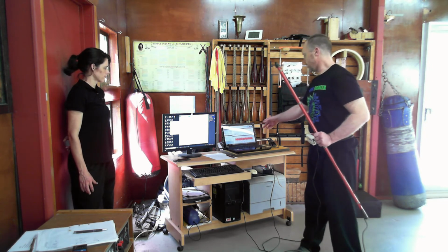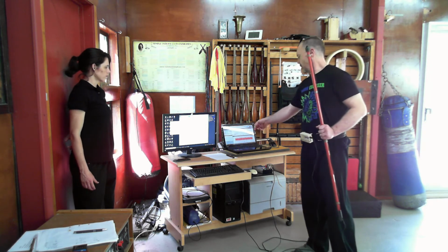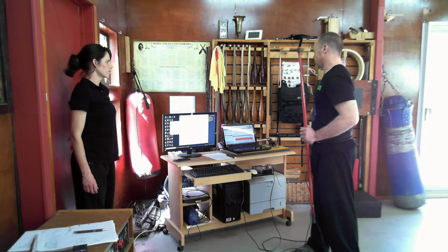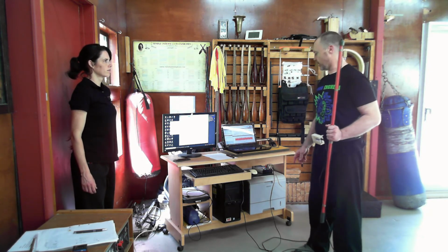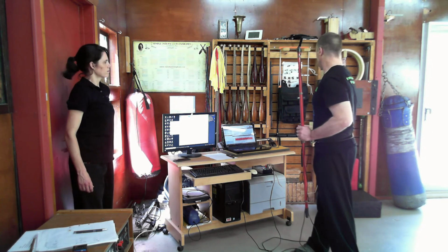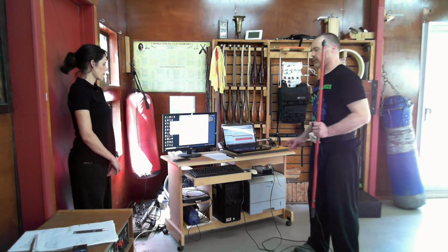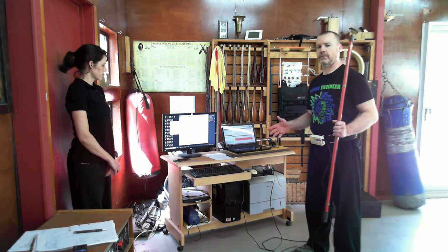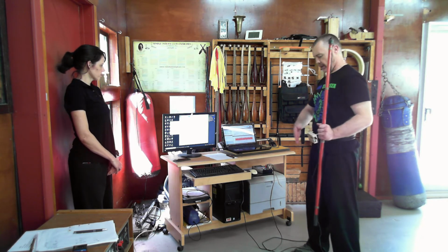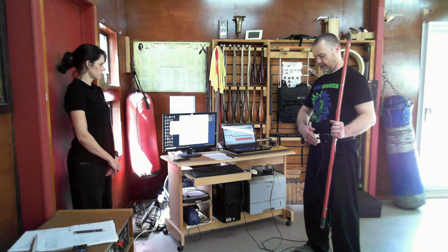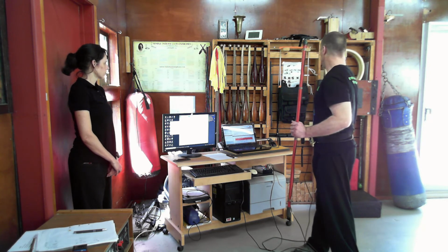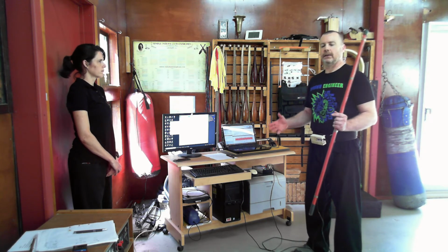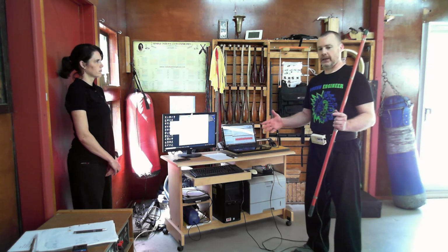In addition, I've got the load cell connected up to this computer, and it's going to be recording force from that load cell. But we're actually not interested in force in this case. We're really just interested in using the load cell to pick up when I press the button, so that we can backtrack and extrapolate time data from that to time align these two devices, the sensor here and the pushing of the button there, so that we can essentially make all of the data time aligned.